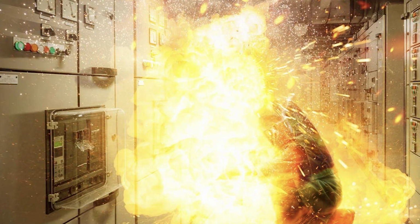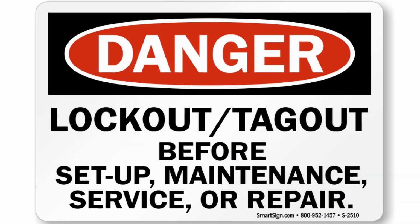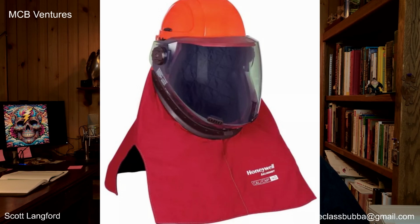Finally, arc flash or electrical hazards. Electrical discharge can cause burns, blindness, or other injuries. Mitigation plan would include elimination, de-energize circuits before starting work. Engineering controls, use insulated tools and barriers. Administrative controls would provide proper training and signage and implement a lockout-tagout program. And finally, use arc-rated face shields and safety glasses.